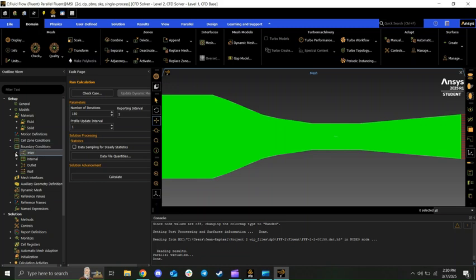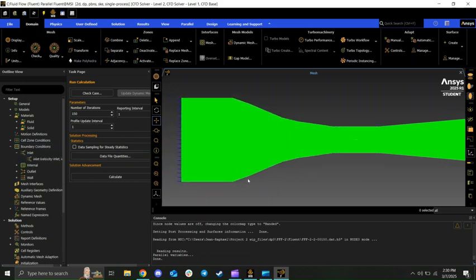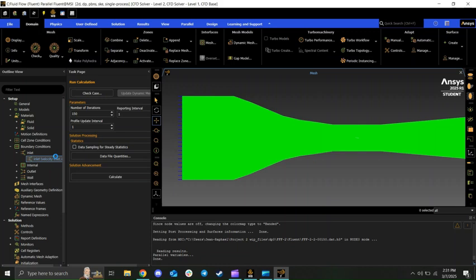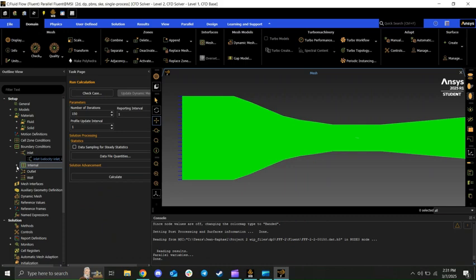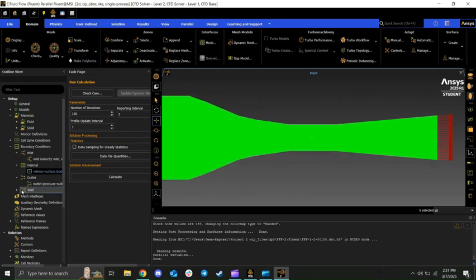Boundary conditions, we would go to our inlet. So you can see here, I renamed it the velocity inlet. We would double click, and here is where we would put the velocity coming into the wind tunnel. In this case, from our calculations, we saw it was 4.522. So we put in that, we apply, close, just making sure everything else is working. We have our interior surface body, our outlet, a pressure outlet on the side here, and then our walls, which would be first the walls of the wind tunnel and the flat plate itself.